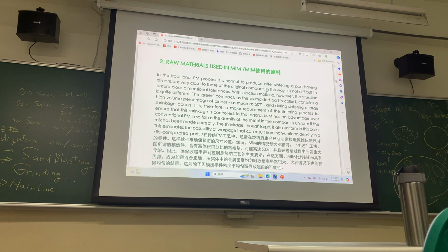Yeah, because with the ball, the surface is too smooth, and cannot be caught by the binder. It separates. So when you mold it, you will get it here this way, and on the other side, the density will be lower because the powder cannot go there. The binder goes more and more, and the powder goes less. So the density on this side is higher, and on this side is lower. This is the problem. So we need to control everything like this.